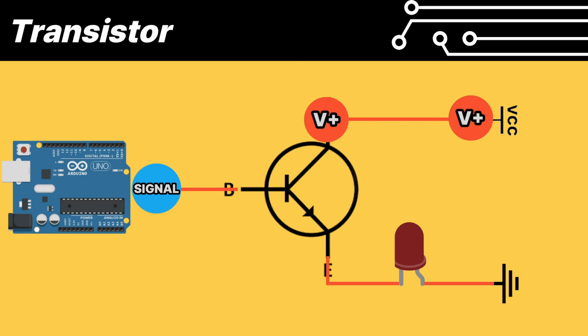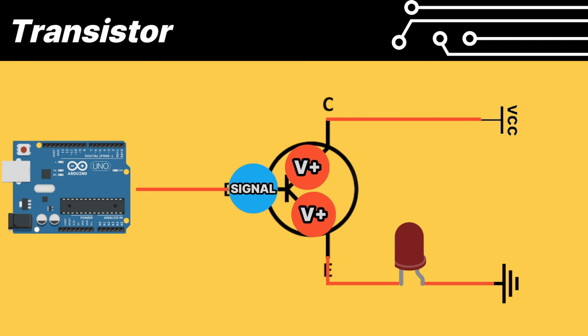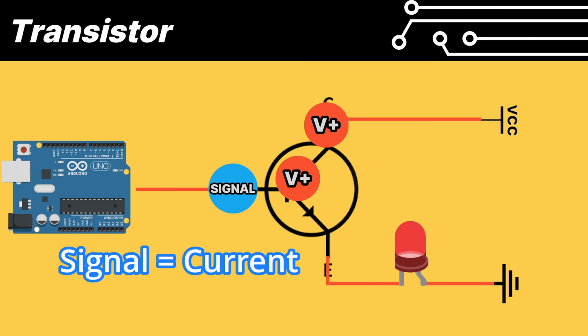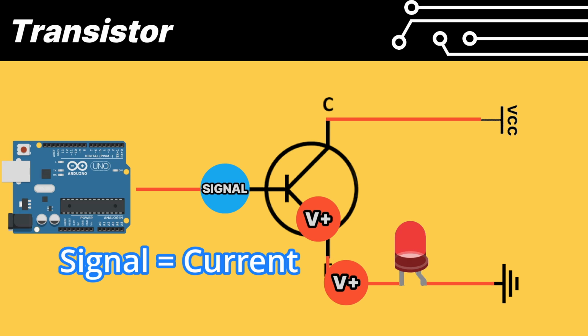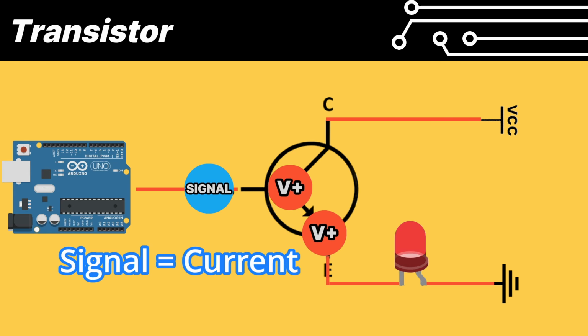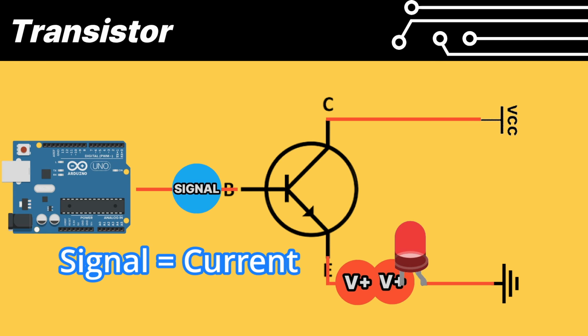The ultimate reason for using a transistor is to control the main circuit with a weak current. This is a current control method. Its advantage is its switching speed, which cannot be achieved with small relays or general mechanical switches.